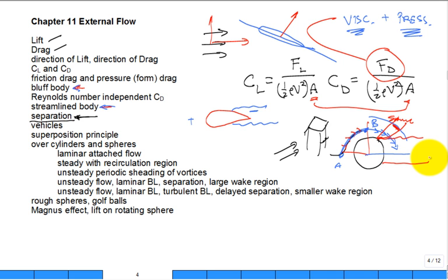It's really good not just to listen to me talk through it, but that you master that concept, because I really think that will carry you a long way to understanding the behavior of fluids. So when you have a bluff body, when you have a lot of separation, the wake region there, you can get what they call Reynolds number independence for the drag coefficient.